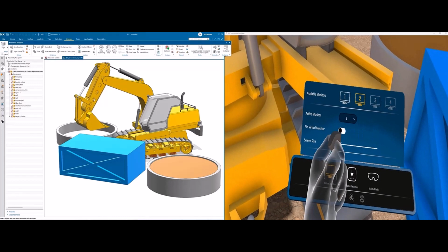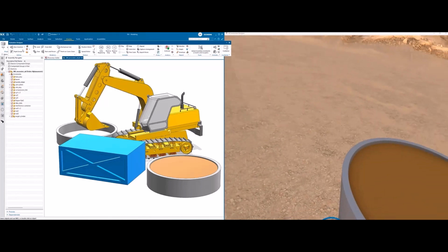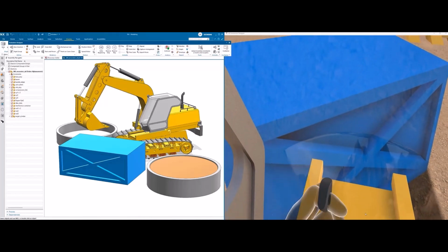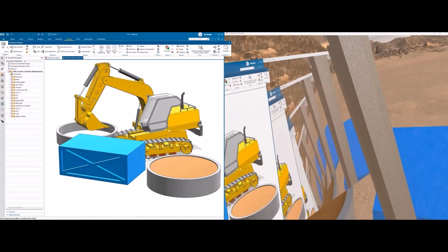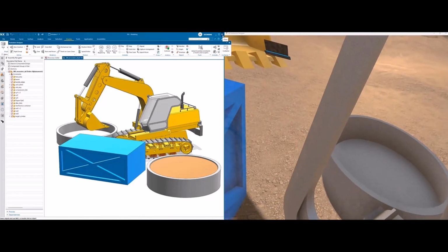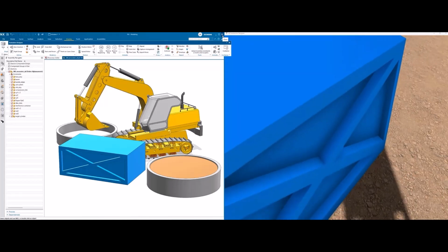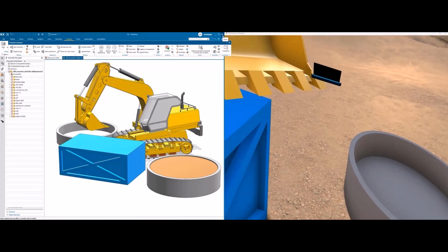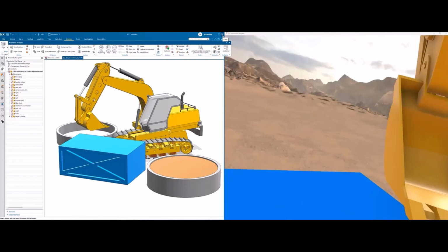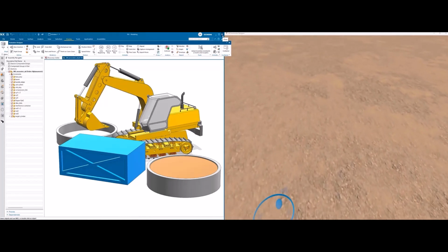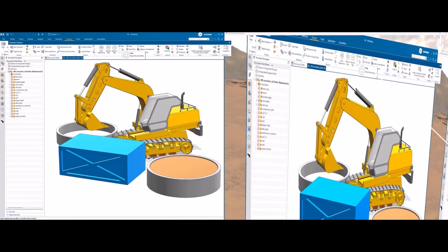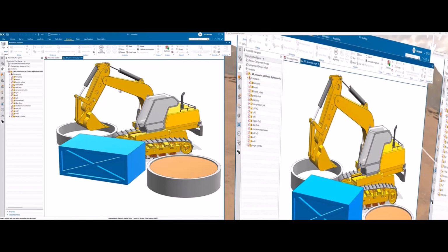What I want to do is navigate into the cab. One of the studies I really want to do gives me this ability to take a look as a cab driver at what kind of viewing capability I will have. So I move my monitor out of the way. I look to my left, I look to my right, and then I also move forward. This is what kind of viewing I will additionally gain from moving from under 1100 millimeter all the way to 140 millimeters. So that gave me some idea of what kind of additional viewing capabilities I will have.